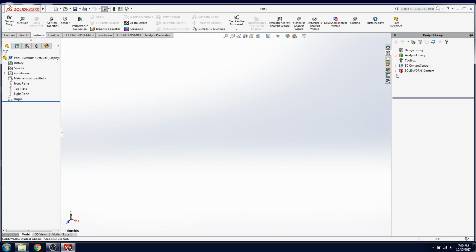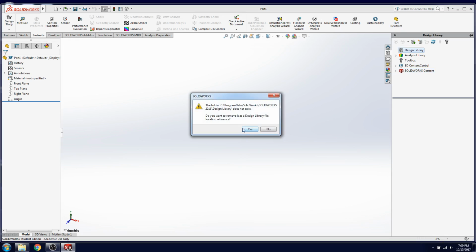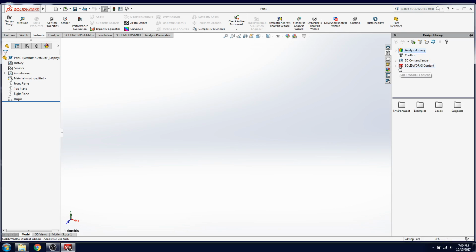We go here to Library, we go to SolidWorks Content, and when you do this, we'll need to look for the last subdirectory that is called weldment, and you see we have different types of weldments. We can use like ISO or Great Britain or German standards, but we will be using ANSI.